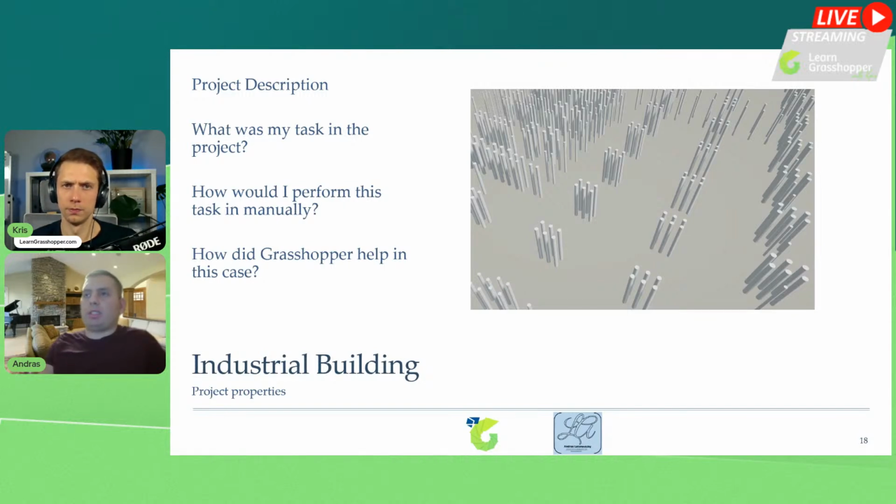I believe this task would take longer to complete using manual methods. For example, we all know phases are added one by one in the phase manager in Tekla. However, with a good script, all of this can be done faster.